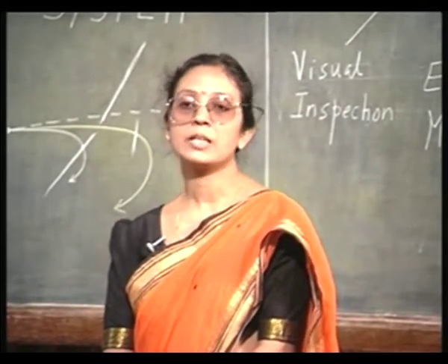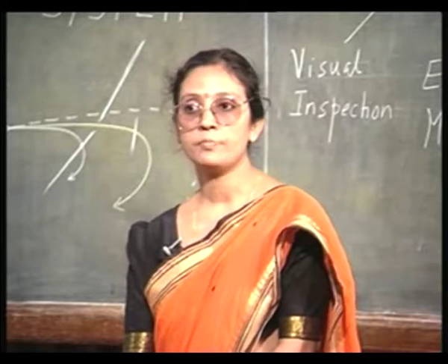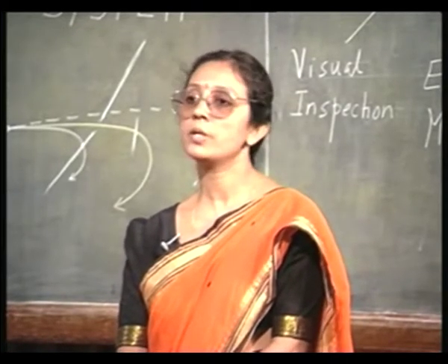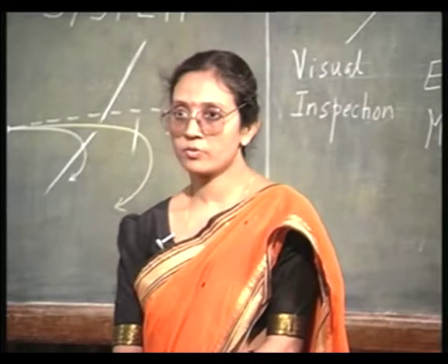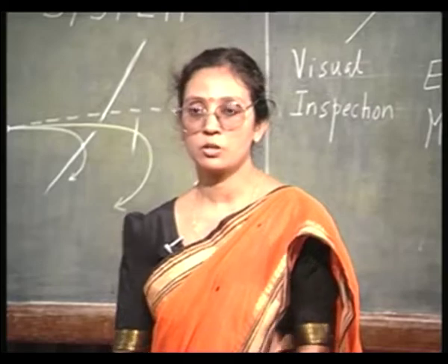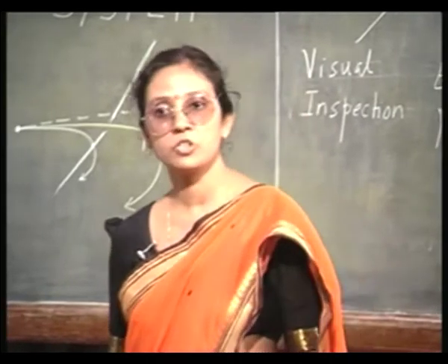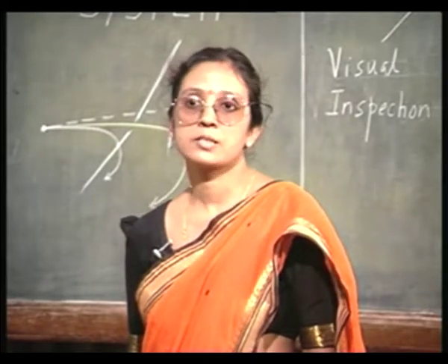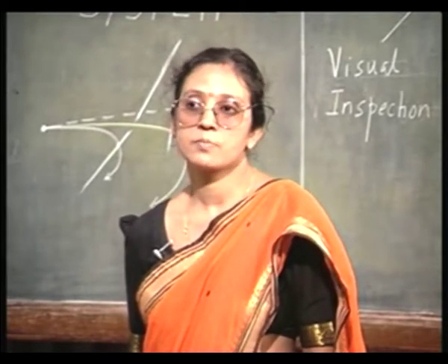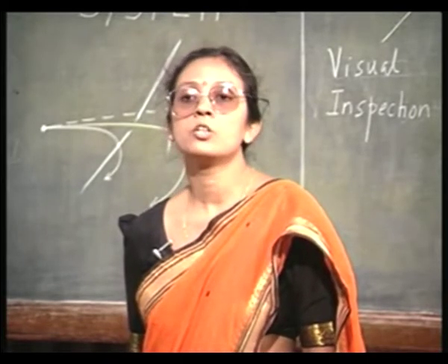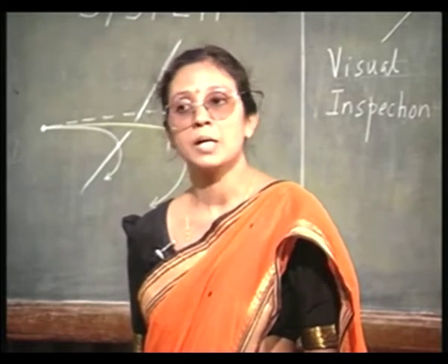Obviously, for light ions, for example boron, the dose required to amorphize the silicon will be much larger compared to phosphorus, because I have to create the same amount of damage in order to amorphize the region. Since boron is a much lighter ion, the creation of damage is much less. Therefore, in order to amorphize silicon, the dose of boron must be much heavier.